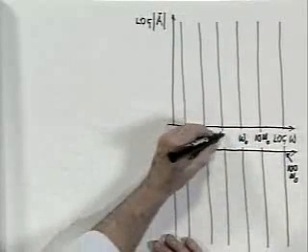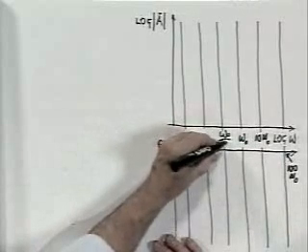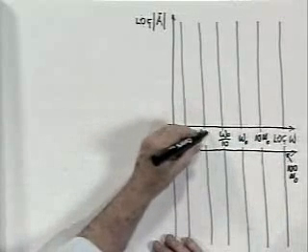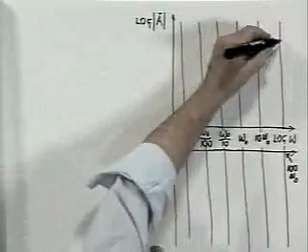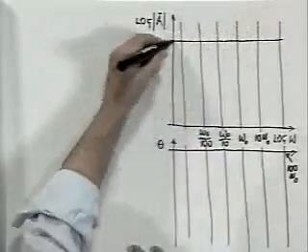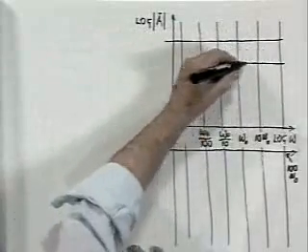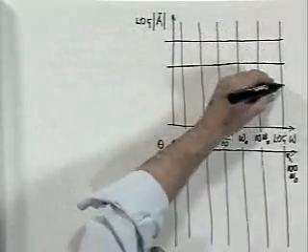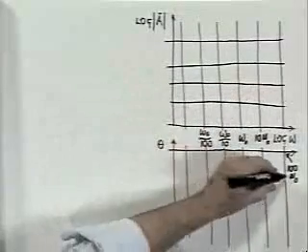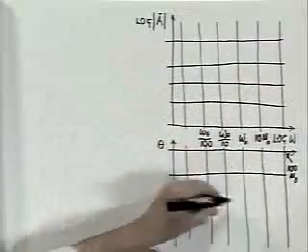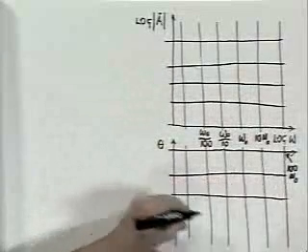This is omega naught over 10, and this is omega naught over 100. And let's assume that again, I want to draw these so that the boxes are approximately square, so that they represent a decade vertically and horizontally. Down here it's less critical. It's a linear scale.